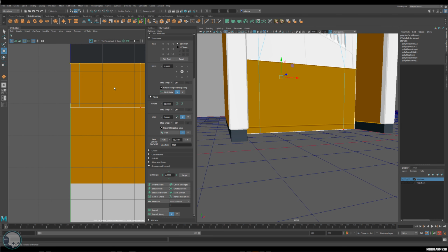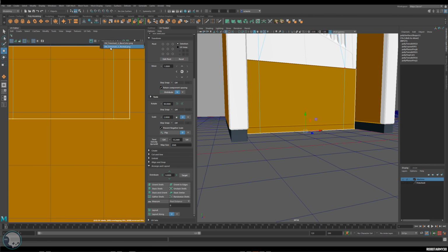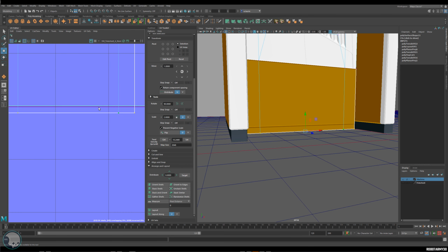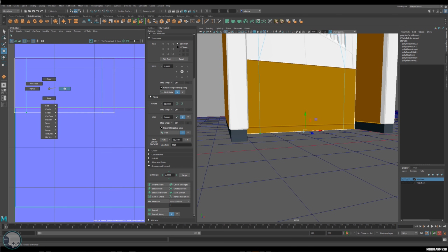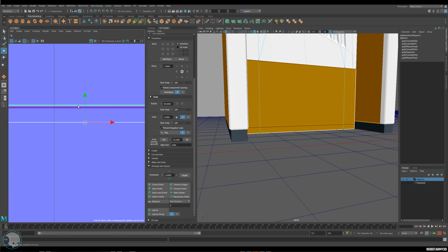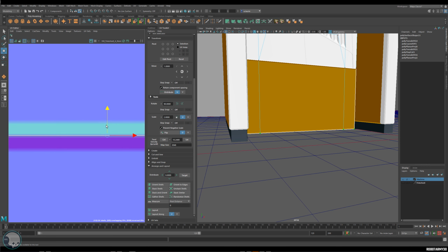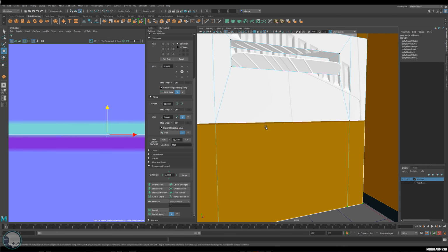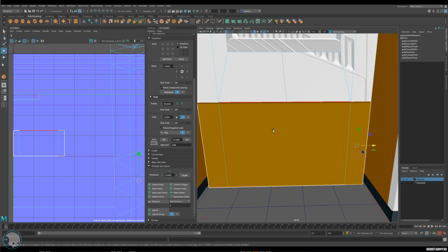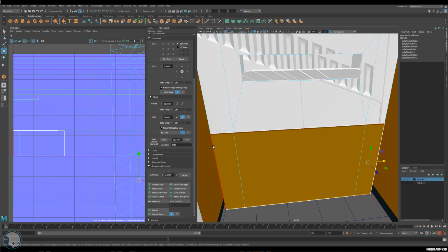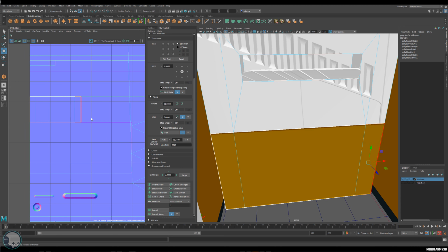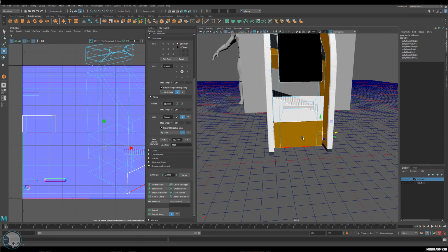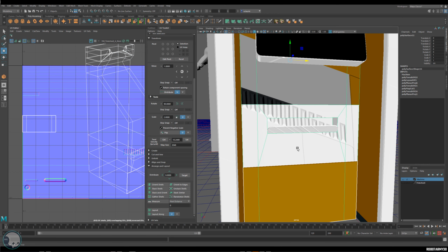Now we still need to stretch this a little bit, I think. So I'm going to grab the bottom of this. I'm going to switch over to the normal so I can see that other panel loop, and I'm going to squash this up a little bit here. So I need to go UVs rather than vertexes, and then move that to match that panel. And you want to get this as accurate in between those two pieces as possible. And we can see that in our scene there. So you can see that little panel bevel at the edge of that there. Okay, so there is no panel edge on there, which I would have liked. So I think I do need to cut this up into boxes so I can more neatly apply that. But we'll come back to do that later anyway. For now, we can just fill out the rest of this.